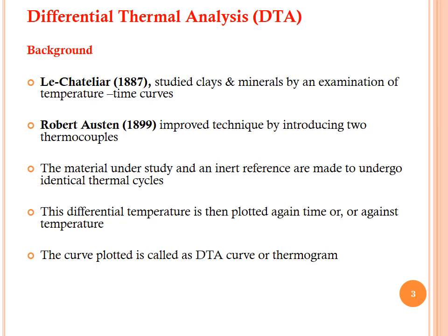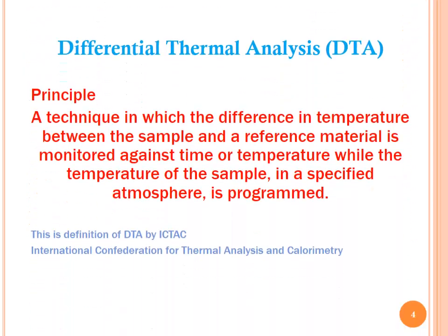The material under study and an inert reference are made to undergo identical thermal cycles. This differential temperature is then plotted against time or against temperature, and the curve plotted is called a DTA curve or thermogram.